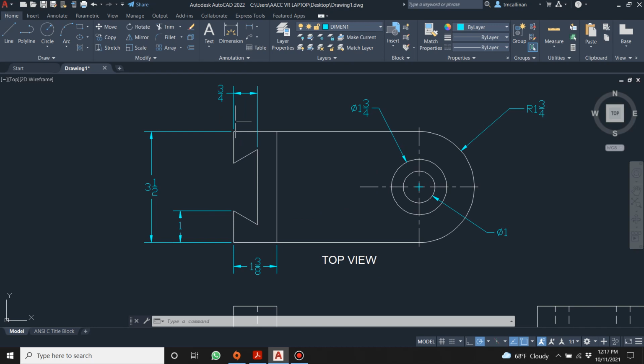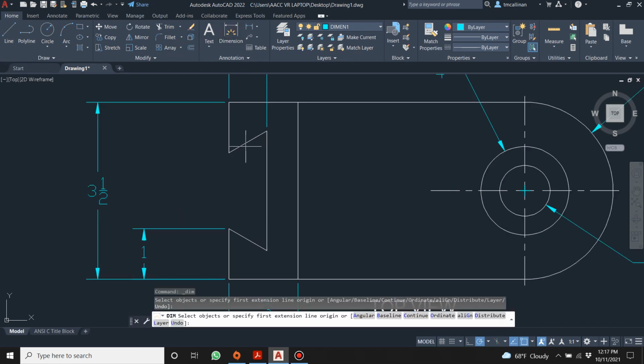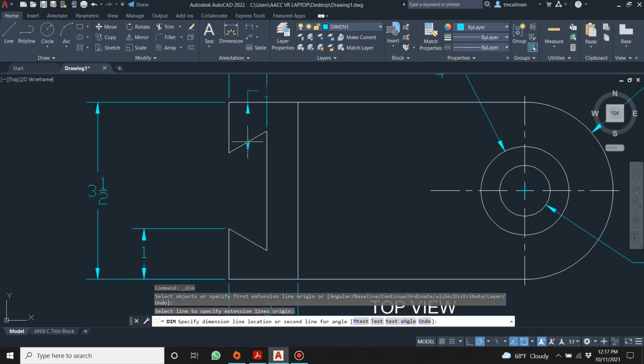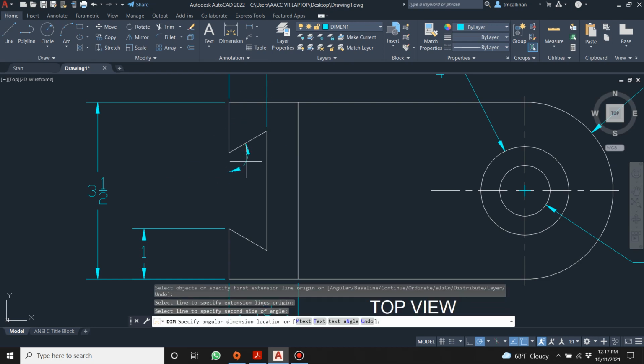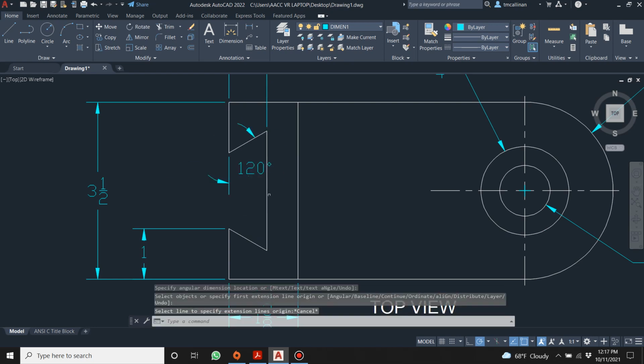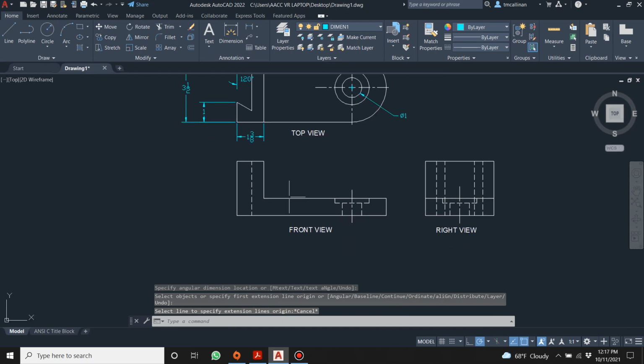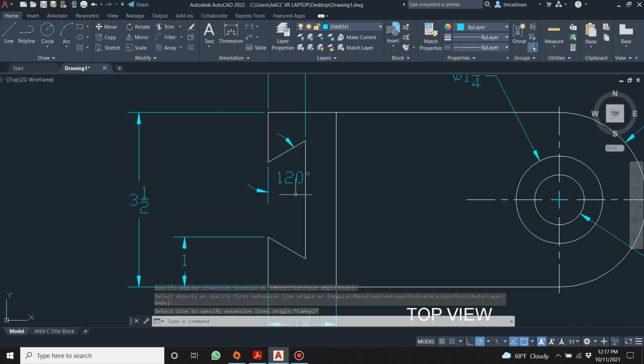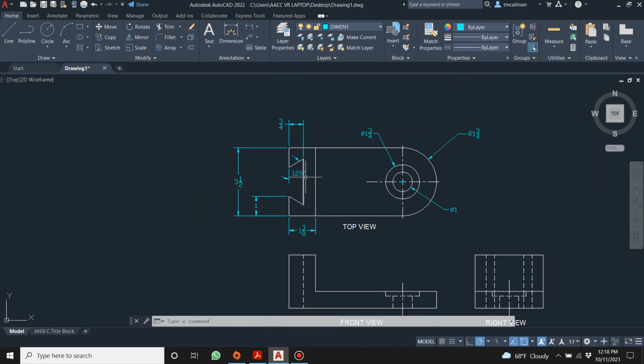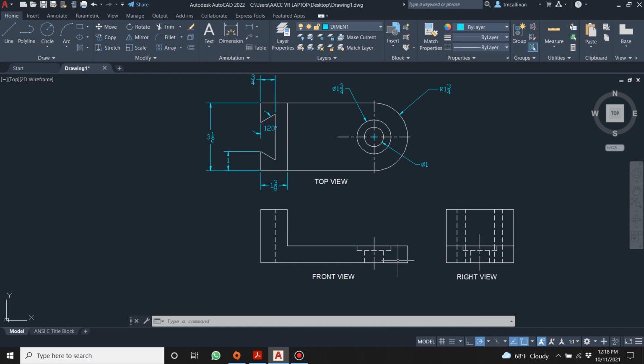A machinist would probably politely ask you, look, Tim, just give it to me in decimal next time, I don't have to think as much. Now, we need a little 30-degree angle. So from there to there, well, 60. This will even do 120 degrees. If that's 120 from there to there, that means that's 60 from there to there, which is correct. If we drew a horizontal line, we'd get that 30 degrees, but 120 does the job, so don't worry.